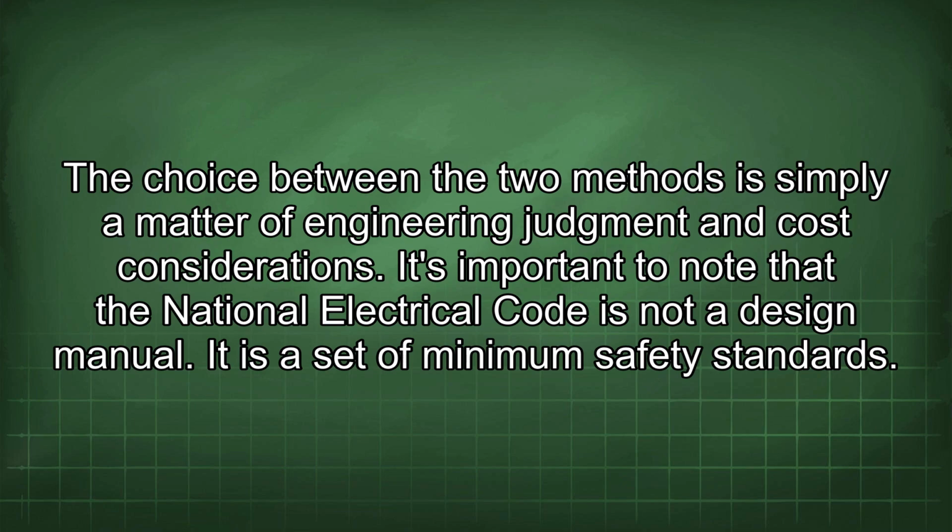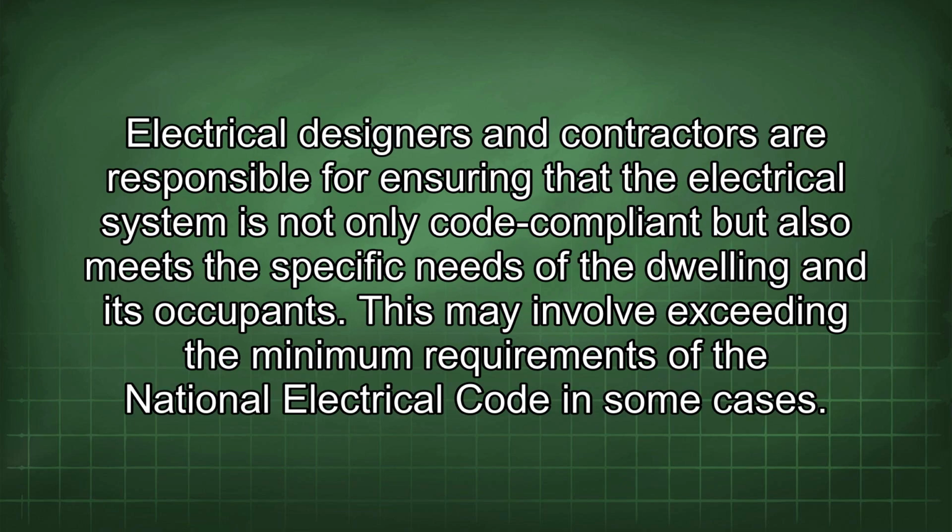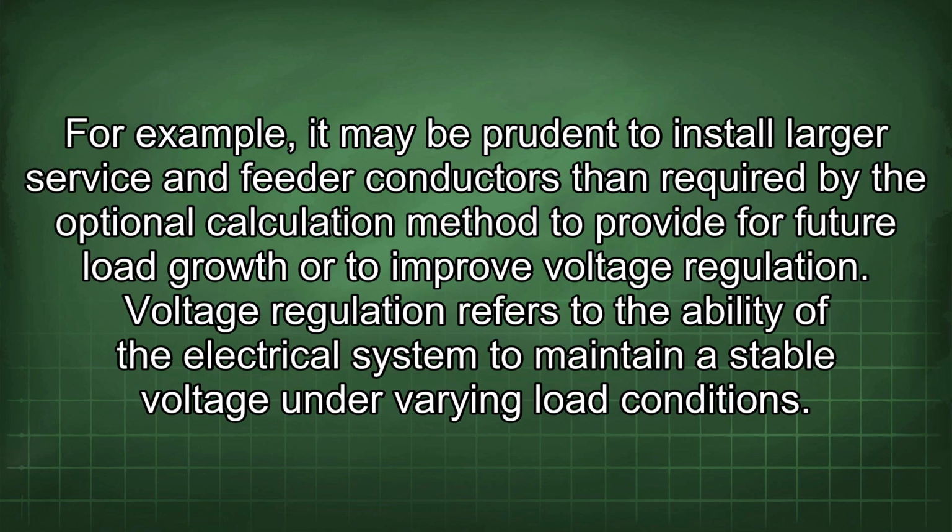It's important to note that the National Electrical Code is not a design manual. It is a set of minimum safety standards. Electrical designers and contractors are responsible for ensuring that the electrical system is not only code compliant but also meets the specific needs of the dwelling and its occupants. This may involve exceeding the minimum requirements of the National Electrical Code in some cases. For example, it may be prudent to install larger service and feeder conductors than required by the optional calculation method to provide for future load growth or to improve voltage regulation.